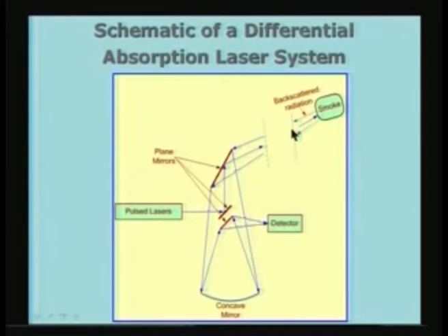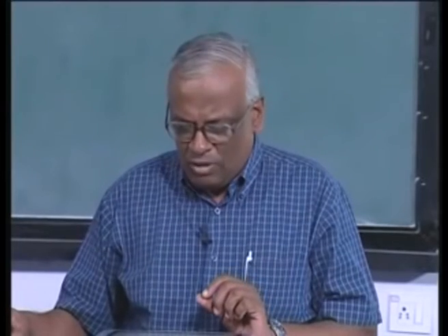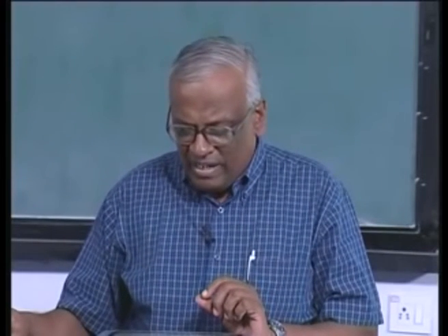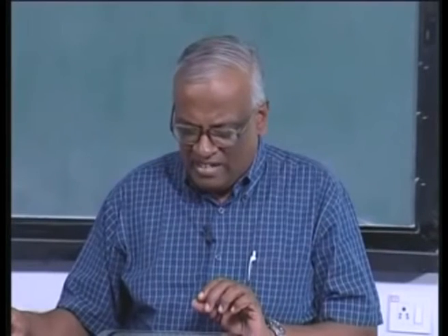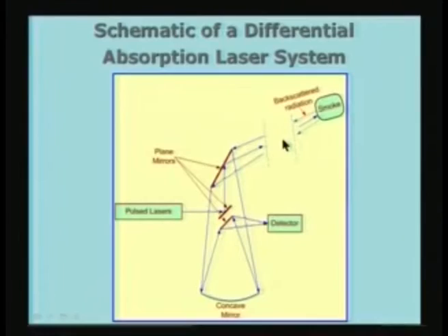So, I will choose the time delay, and also the gate, the time over which I am going to make the measurement, such that I can specifically find out what is happening in this particular region between these two dashed lines which I have shown here. Okay. So, what happens in this case, the return signal follows the forward path and it comes back.